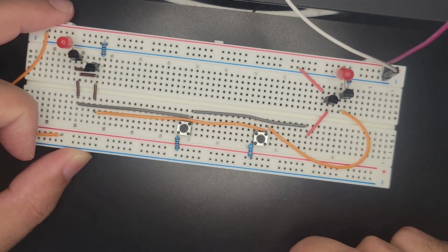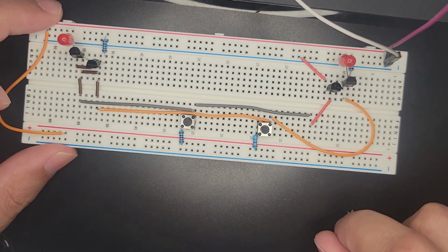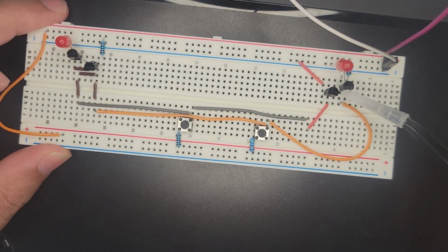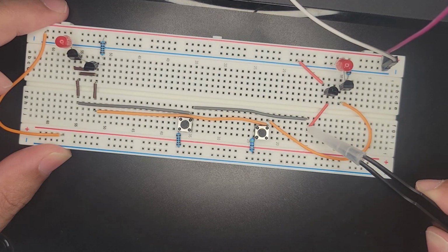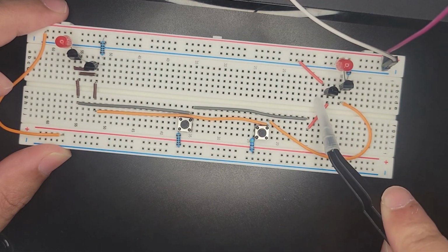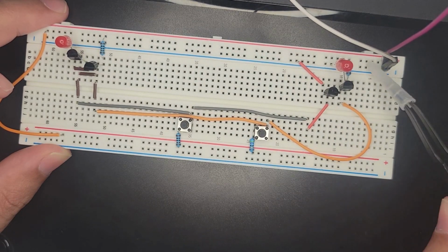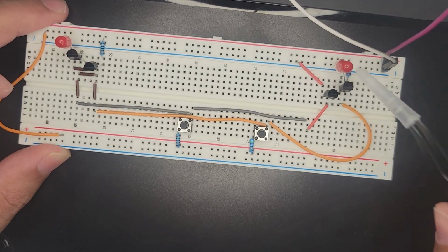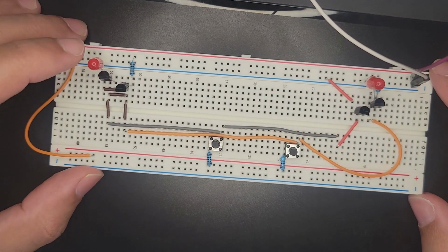But let's see if it works. All right, so these guys are connected. So we have a resistor going to collector A, which outputs out the emitter when activated to collector B, which, when activated by B's button, will go to ground, creating a cheap path to ground, skipping the LED, turning the LED off. If this path is not available, the LED will be on. So I think that properly satisfies our requirements for a not AND gate.